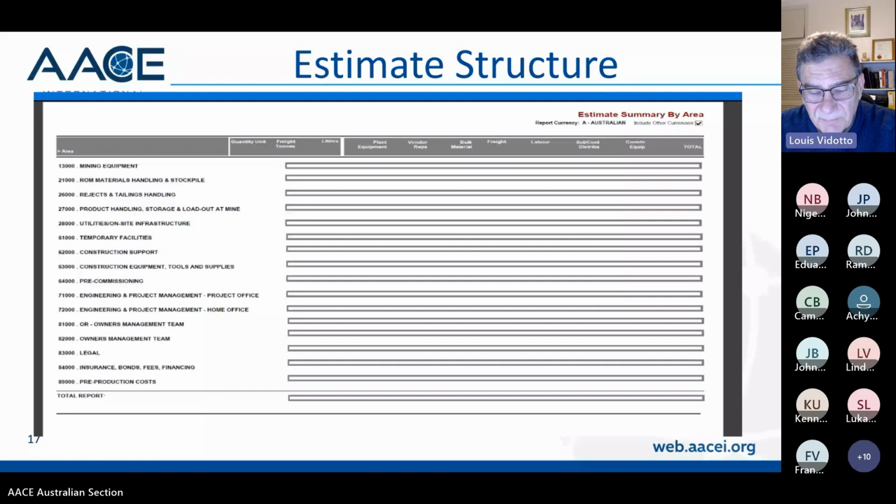and then calculate it out that way. The way that I've done it at a high level is really to look at the overall schedule from the base date to the end of construction and do a centroid of expenditure. So 2/3 along the way of a project, very simplistically, you've probably spent half your money, and then how far is that along your schedule, and then use things like a CPI or a published escalation rate that they think is going to happen. So depending on what your requirements are from your owner, you can either do it very detailed, or when you're an estimator, particularly during feasibility studies, you might look at just doing a centroid of expenditure. And I'm happy at some stage to go through and show you what that looks like.